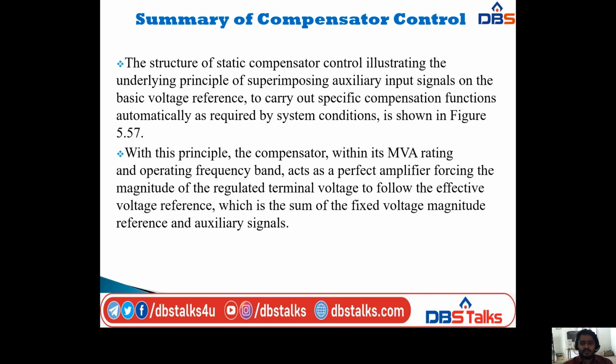In this concept I am taking the summary of compensator control. Up to now we discussed var reserve control, that is the last characteristic of the SVC and STATCOM, and now we are moving to the next concept, that is the summary of compensator control. The structure of static compensator control illustrates the underlying principle of superimposing auxiliary input signals on the basic voltage reference to carry out specific compensation functions automatically as required by system conditions, as already shown in this diagram.